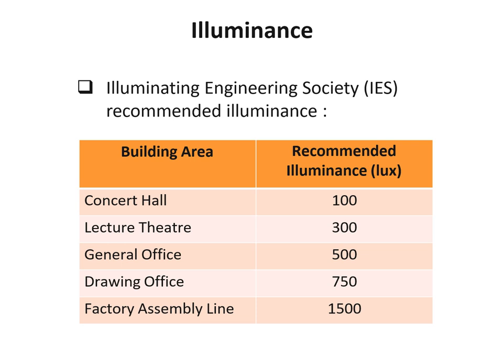There is a recommendation for the illuminance based on the building, the function of the space, the type of the building, etc. These are generally just to illustrate the difference in recommendations for lux level. The list is very extensive. So for example, for concert halls, recommended illuminance is 100. Try to imagine a concert hall. Marina Bay Sands is not a good example actually. If you think about Esplanade, when you're in the theater space, in the concert hall, the feeling of that space will be 100 lux.